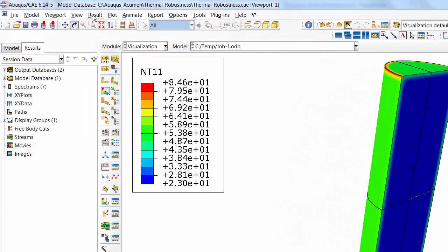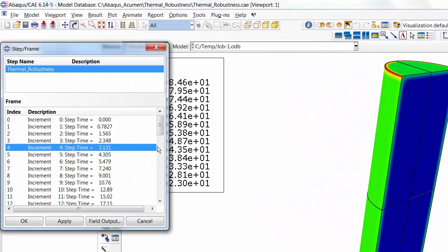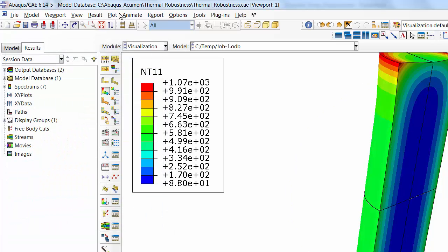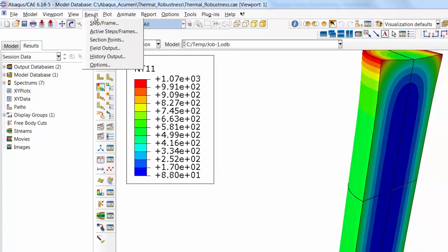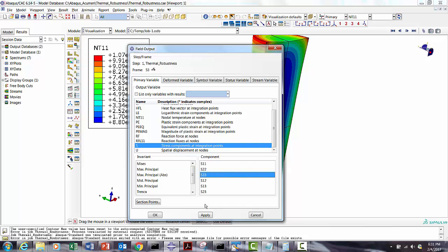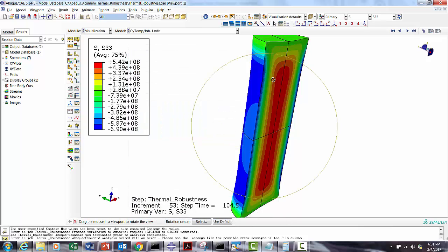And because of thermal expansion you get axial stress. For this particular case it will be axial stress generated, and this axial stress is because of thermal expansion. So we'll also have a look into axial stress. You see, because it's moving out, axial and radial, the core is getting tensile stress, and this is in Pascal. You may be surprised why this high number. It is in Pascal. We are going to use kg, Newton, meter. So we'll go to the problem now.